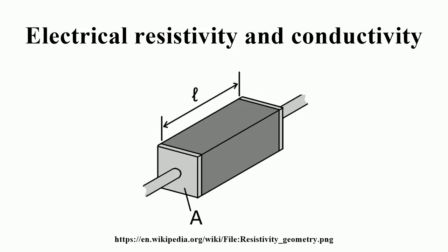In metals, the Fermi level lies in the conduction band, giving rise to free conduction electrons. However, in semiconductors the position of the Fermi level is within the band gap, approximately halfway between the conduction band minimum and valence band maximum for intrinsic semiconductors. This means that at 0 Kelvin, there are no free conduction electrons, and the resistance is infinite. However, the resistance continues to decrease as the charge carrier density in the conduction band increases.